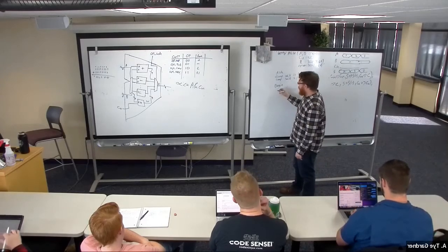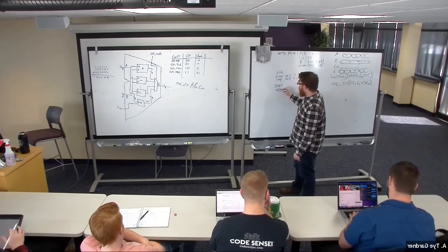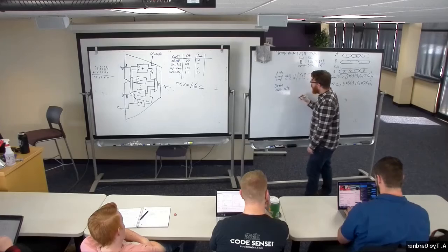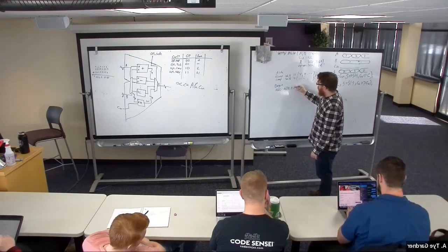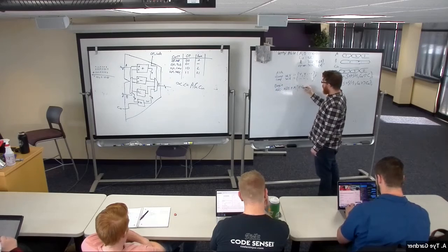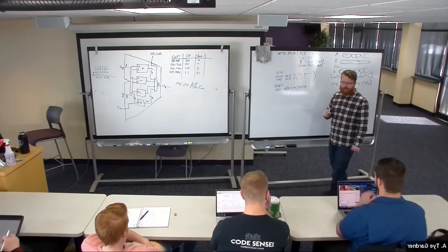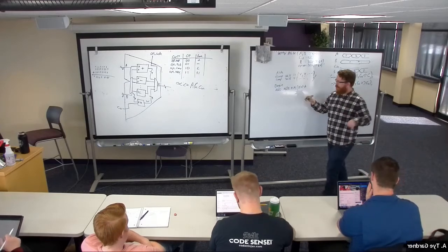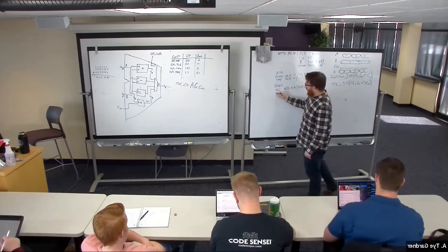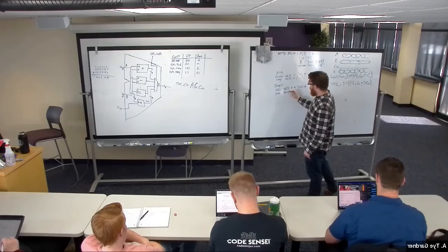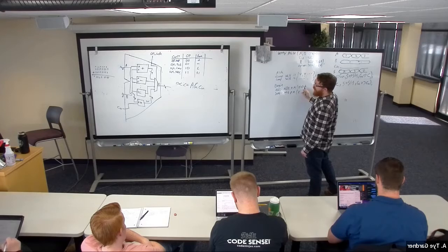So call it add 0 is a component of add 8 whose port map is, well, it has a port X that's getting mapped to A. A is 8 bits, X is 8 bits. I'm good. Fill in the rest of the port map, then I'm going to have sub 0, which is sub 8 with a port map, not X.